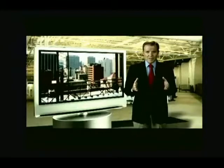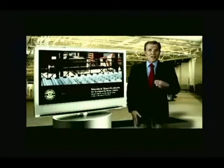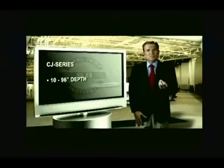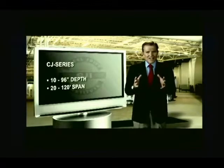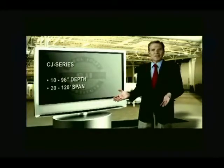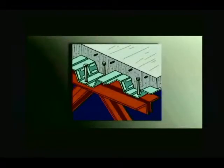The open web composite steel, or CJ series joists, with parallel cords only, are capable of supporting larger floor or roof loads because a concrete slab is attached to the top cord. This creates composite action between the steel joist and the concrete slab. The shear connection between the concrete and the joist is made by welding shear studs through the steel deck to the underlying CJ series composite steel joist.